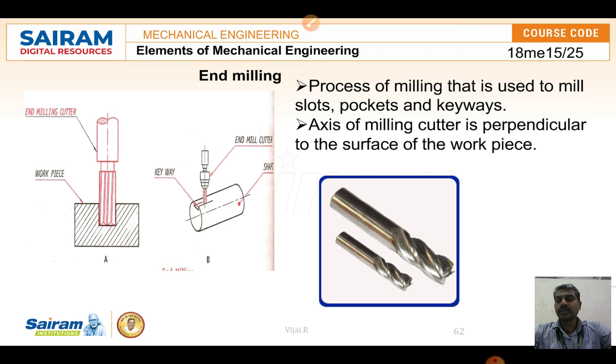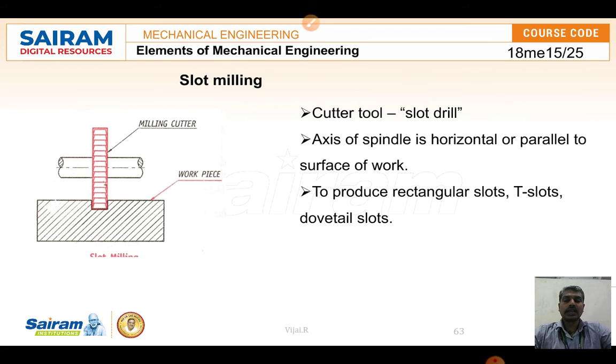It is a vertical milling cutter which has teeth on the entire circumference, and it is rotated while the workpiece can be moved to and fro, so that it can create a groove or slot, whatever it is. We can make it by using an end mill cutter.